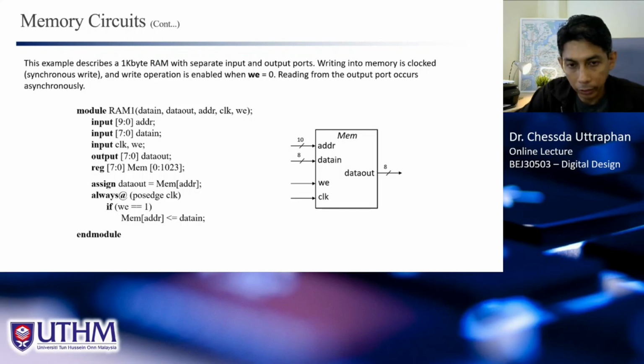And also we learned the application of the register where we can shift the data, and we also learned another application of register where we can create the counter. So the counter, we can create the up counter and down counter. To create the down counter, you just change the adder into a subtractor, then you can get the down counter.